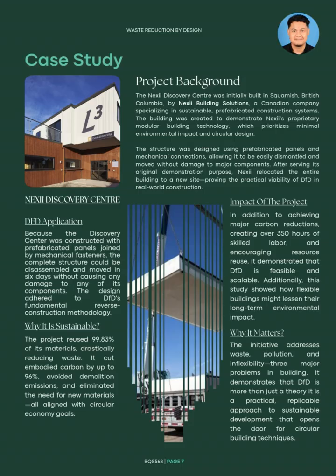To see design for disassembly in action, I studied the NETC Discovery Center in Canada. This modular building was designed using disassembly principles, with prefabricated panels and mechanical fasteners. After its first use, the entire structure was disassembled in 6 days and reassembled at a new location. Over 99% of materials were reused and emissions were significantly reduced, proving that design for disassembly works in real-world projects and not just in theory alone.